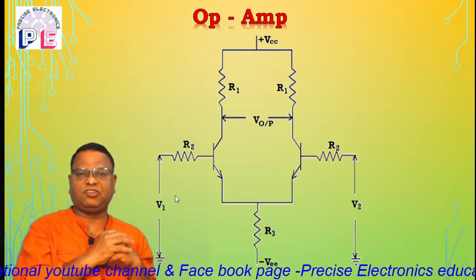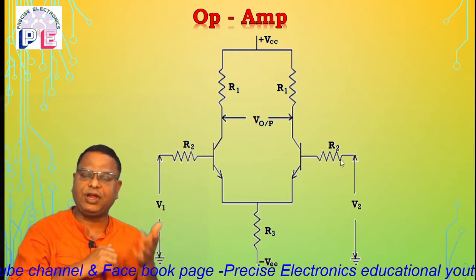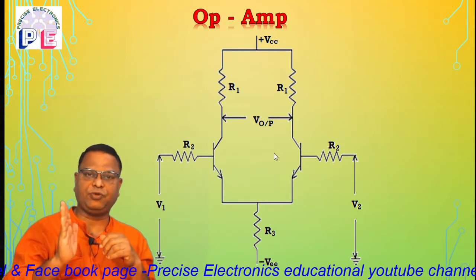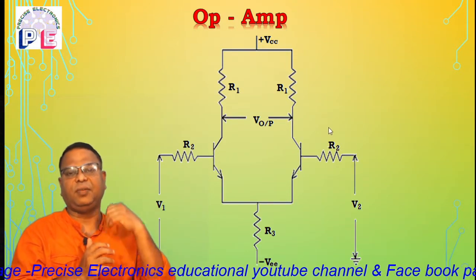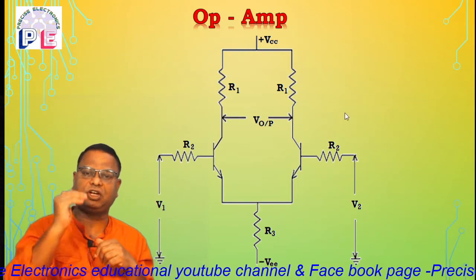The bases of the transistors are connected to input signals V1 and V2 through input resistors R2. V1 is connected to the base of transistor T1 through resistor R2, that is the base resistor. Similarly, the input signal V2 is connected to the base of transistor T2.